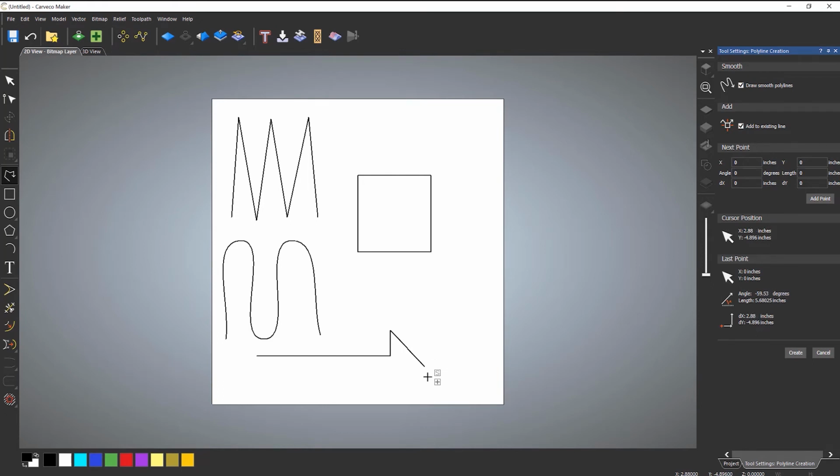Now what this means is this is coming onto something called snapping. So basically snapping locks to a point. So you could do that on the end point there. So if I were to click that there, even though that's not bang on the end of that line, it will automatically go to the end of it because I've got that cursor. And that's what snapping means.